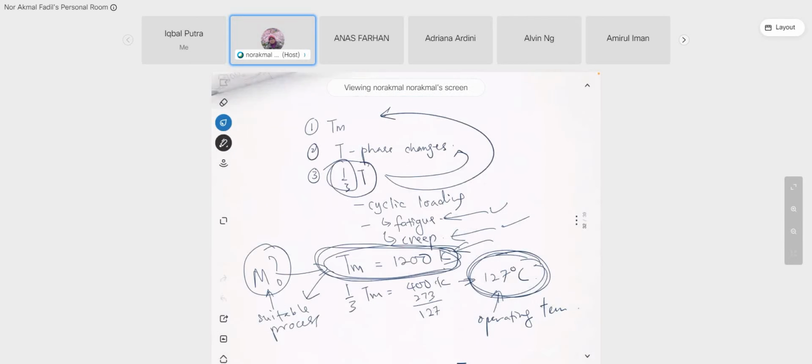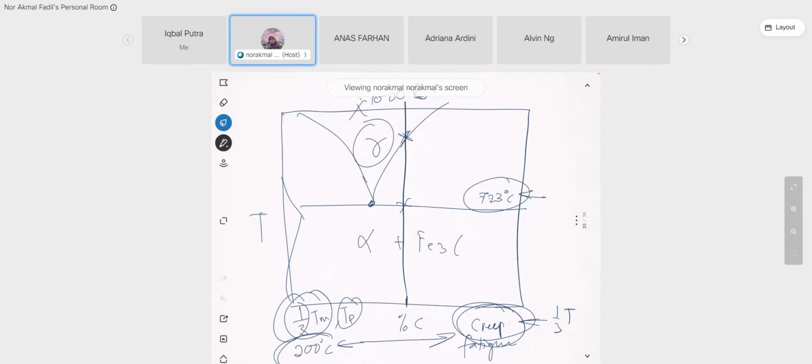for the iron carbon phase diagram, this is an example of the iron carbon phase diagram. This is 0.76 and 0.02. So the pearlite is coming from the eutectoid reaction. For the composition 0.76, you will get 100% pearlite, a lamellar structure like this.